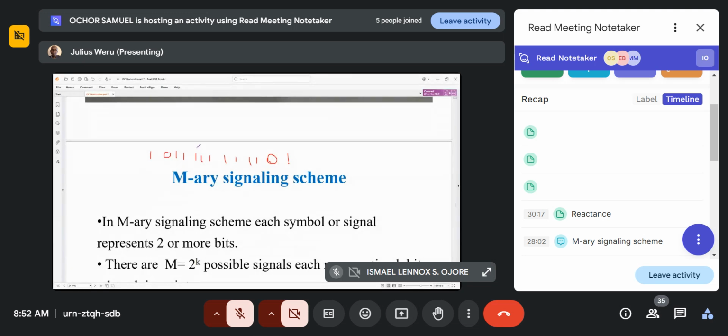It happens in all communication systems, even in cables. So as the frequency increases, that capacitive value, although it is small, because of the omega becomes quite significant. And in the long run, you cannot go for higher frequencies.